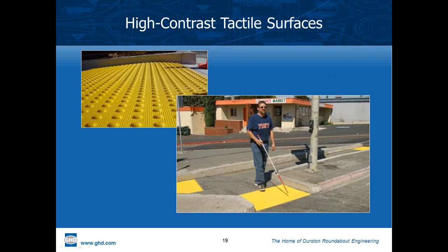The thing about pedestrians with vision loss or partial vision is that it's difficult to find roundabouts, and it's difficult to navigate them if they aren't given good guidance on where to cross and the comfort of where to cross, and having distances shortened in locations where they have to cross. It's also difficult for them to create gaps in traffic. I talked about point and walk.